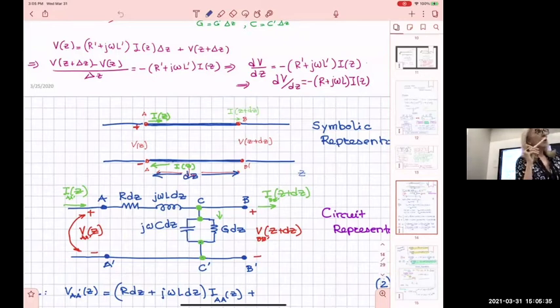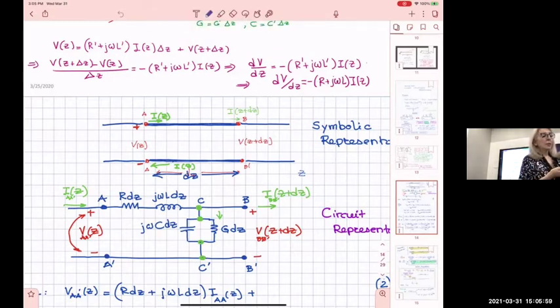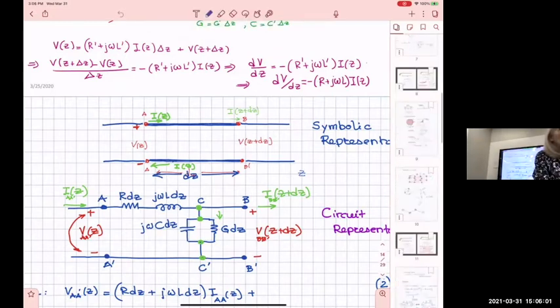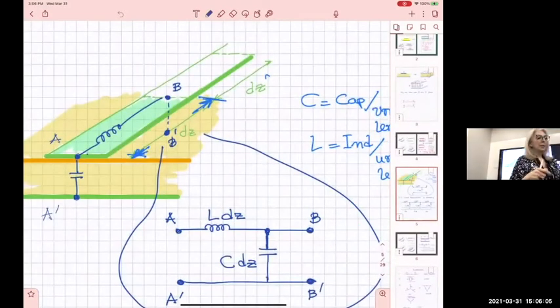But of course, when you go to lines, there is not only one. Over the last 20 or 30 years, people have looked at different types of lines. But the characteristic is the following. In all of these transmission lines, there is one characteristic: they are made out of two conductors. The conductors can be a microstrip like we had here in the beginning, like this. It could be something like that.